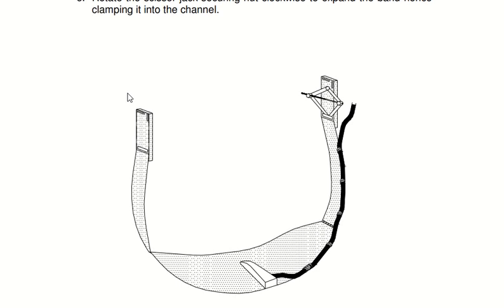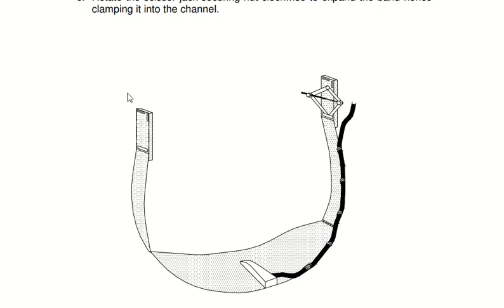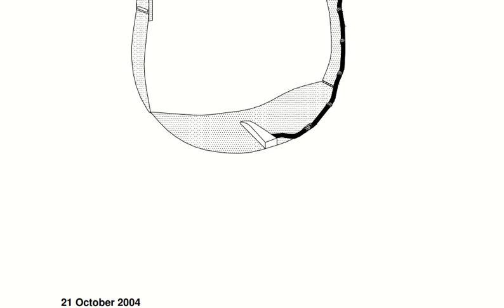After that, you have to put it facing upstream and then fix the other end of the scissor jack to the right hand channel wall with the second through bolt. And in the final step, you simply rotate the scissor jack securing nut clockwise to expand the band. Okay, so what it will do is clamp itself into the channel.